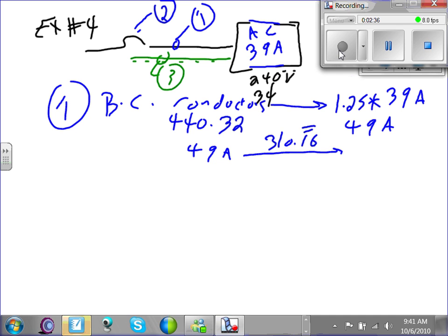You're going to take it to 310.16 under. For HVAC equipment, we don't know it's a motor. By the way, when we did the motor, did we go under the 60-degree column or the 75-degree column? 60? It's okay, but we could have gone under the 75-degree column for motors because of the exception. I'll do one more. I got a question. Yes, sir. 440.32 is for a single motor compressor. So that's 3-phase. Do we have to take into consideration that it might be a Y start delta run? No, not at this time. We're not going to get into the start. This is across the line start.